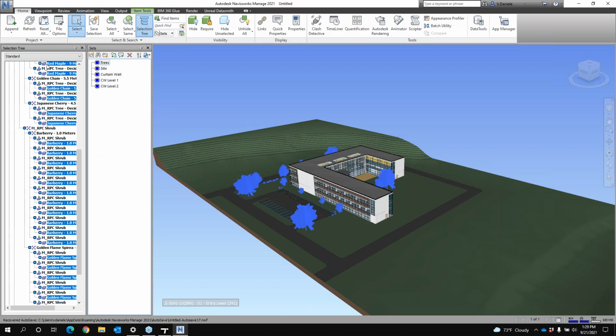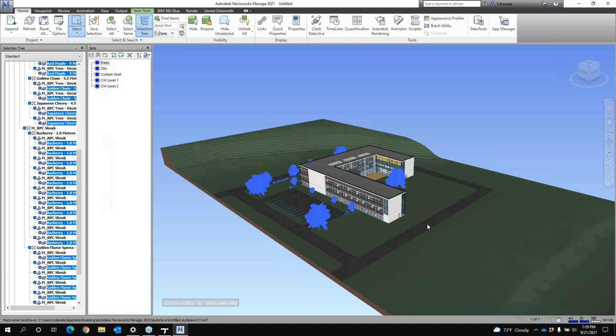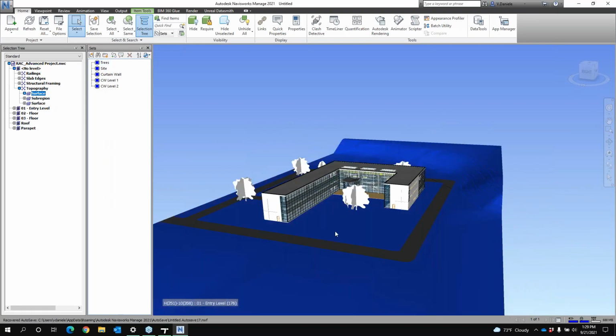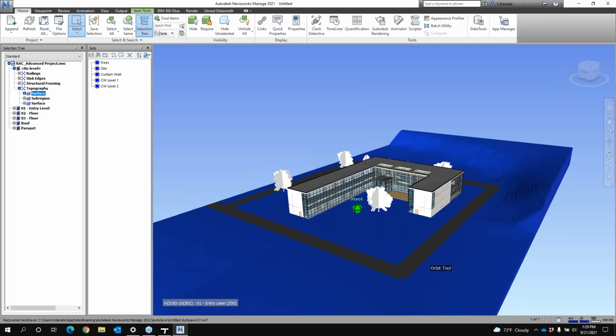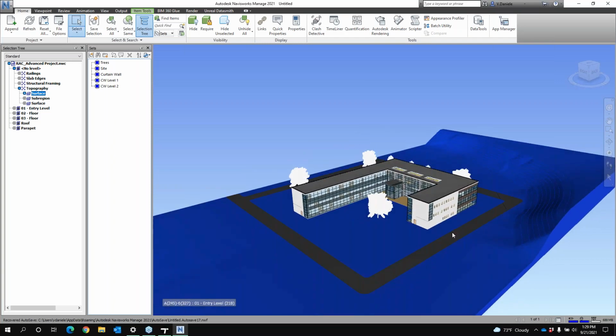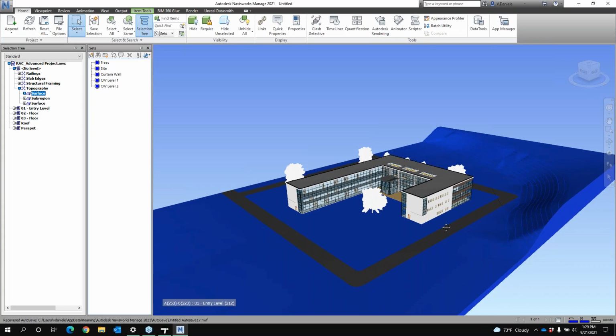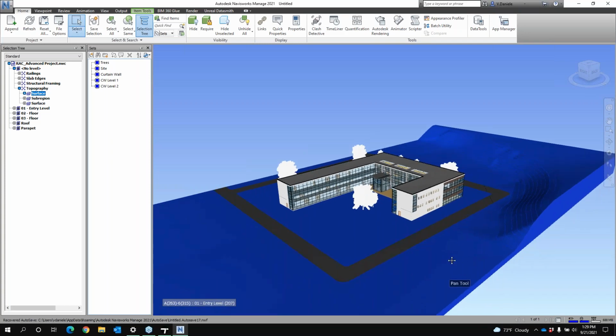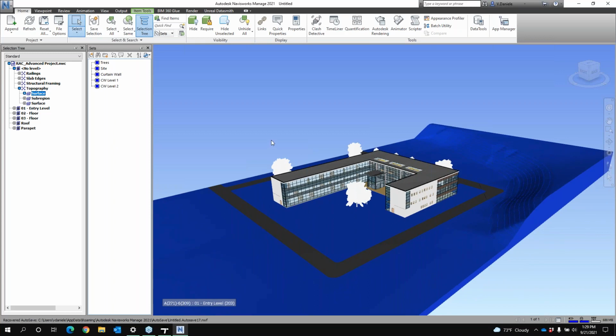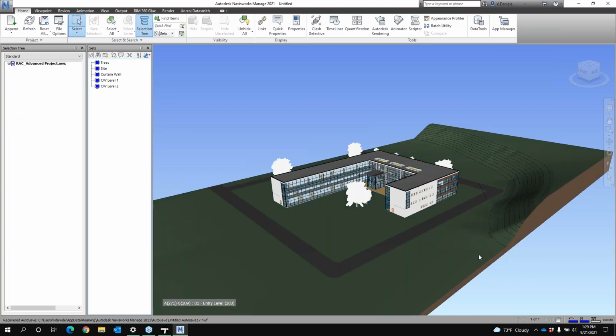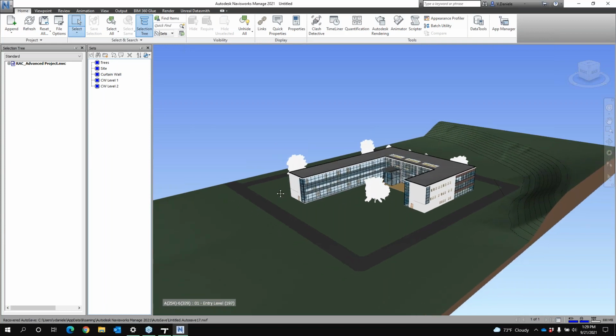selection sets. A hierarchy in Navisworks is very similar to what we're seeing in Twinmotion in the scene graph. It's really complicated, but Navisworks has a number of different controls that make selecting objects from our Revit models much easier than Twinmotion does natively. For one, we have a selection window, which you don't have in Twinmotion. So you can do a big group or a selection window around a number of objects, save it to a selection set, and then export them out.